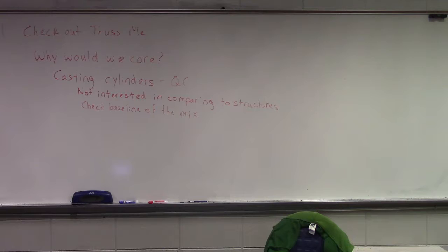That being said, there are going to be times where we have issues with this material in the field. Logan's talking about a specific instance where they had a moisture event after placing. I imagine the first thing they're going to do is test the core for compressive strength, and then they're probably going to cut a section, polish it up, and look at it under the microscope to see if we have any breakdown of the mortar matrix right at that top surface.